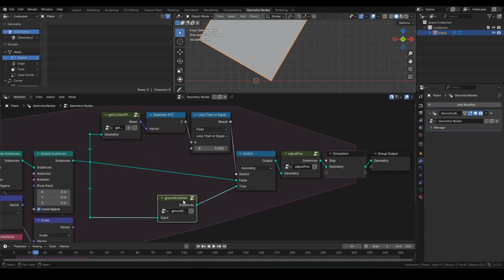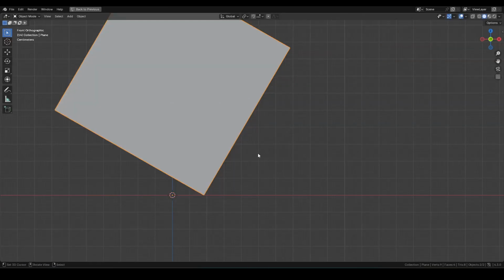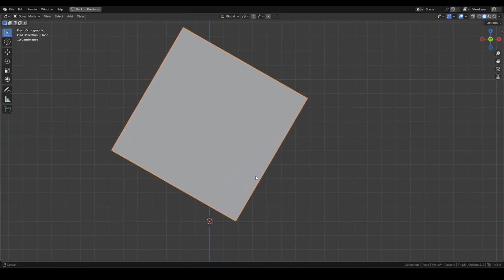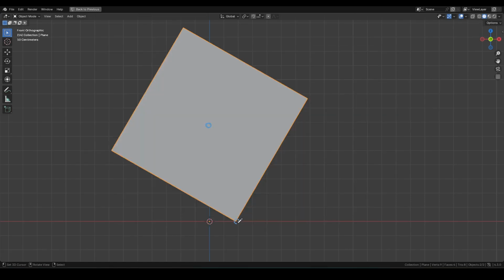Let's go back into node group to make the collision portion. First, we'll consider the linear movement upon colliding. When the center of mass is offsetted from the point of collision, there is a reactive force applied towards the center from ground. In the case of this illustration, the tile will bounce off to the left due to the reactive force. We'll need two vectors to calculate this: velocity and directional vector from contact to center. We should end up with the resulting vector going towards top left.